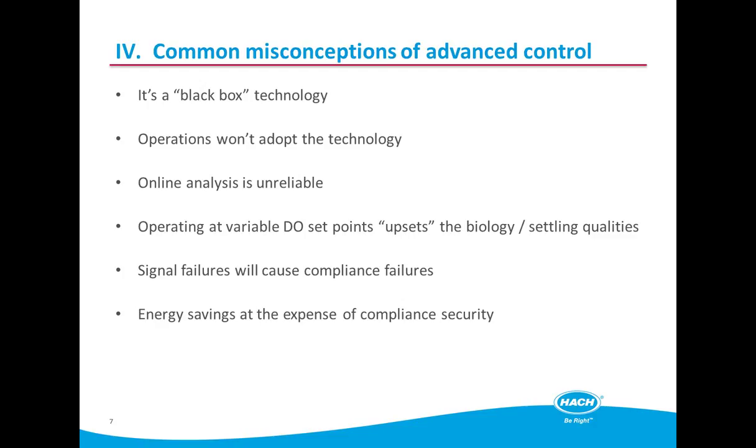Again, as previously mentioned, we work very closely with site staff to ensure that we have specific fallback strategies for the loss of every individual signal into the system. So this allows maximum uptime of the system and ensures that in the worst case scenario, the simple control that was in place before the advanced control is used.